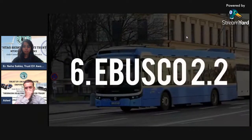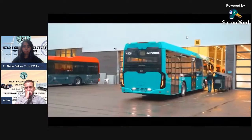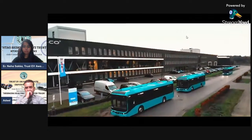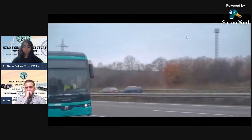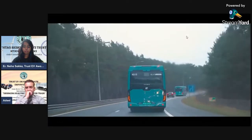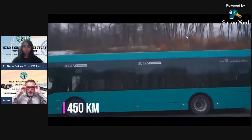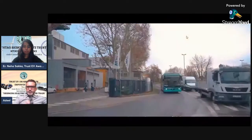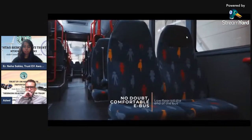Number 6. eBusco 2.2. The eBusco 2.2 is a very innovative electric bus. eBusco supplies the 2.2 in 4 variants: the 12-meter bus, the 13-meter bus, 13.5-meter, and 18-meter bus with its 350 kilowatt-hour battery pack. The eBusco 2.2 can run a range of up to 350 kilometers, and with the optional 400 kilowatt-hour battery pack, up to 450 kilometers. The eBusco 2.2 uses the LFP battery technology, which provides a high energy-to-weight ratio. This battery technology gives the bus a longer useful life and enables battery warranties.